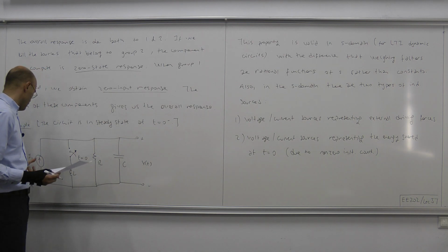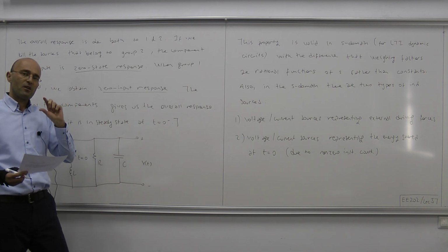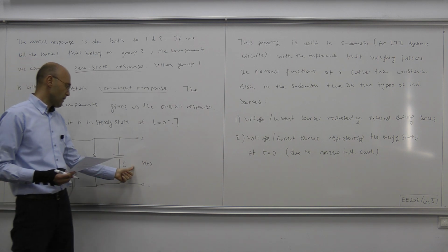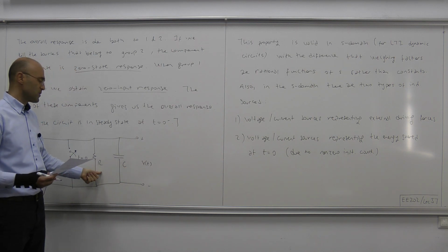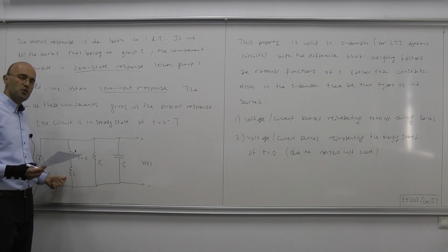So that generates the voltage I1 times R, and that I1 times R will be our initial capacitor voltage. So the initial capacitor voltage will be I1 times R, and the initial inductor current is clearly 0.